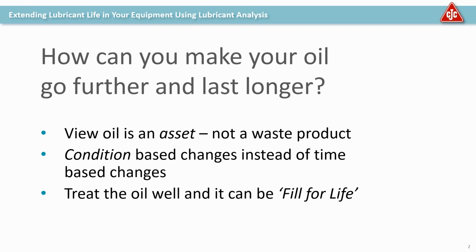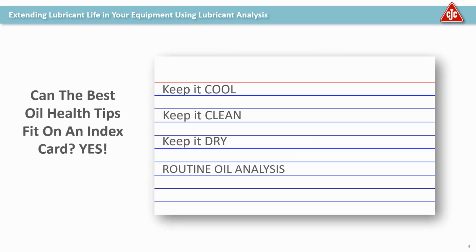It's interesting that the synthetic base oil has a 20-year life in most cases. So it's really not the base oil, but it's the additives, for instance, that are aging, or other properties that we can control that contribute to premature aging. And so with that in mind, then we can start to fill out our own index card, and we can do things very simply. Keep it cool, keep it clean, keep it dry.